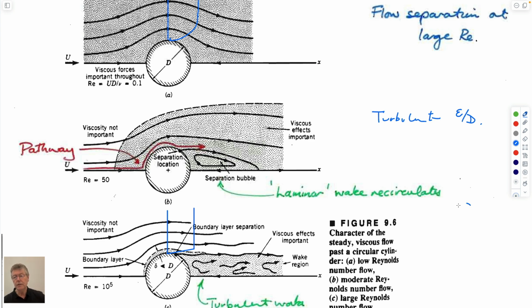So if you imagine this golf ball, not a very good golf ball, having some kind of roughness on it, the dimples on the ball, it goes into the turbulent regime at a lower velocity than it would otherwise, and therefore it goes further because there's less force applied on it as a result of that.